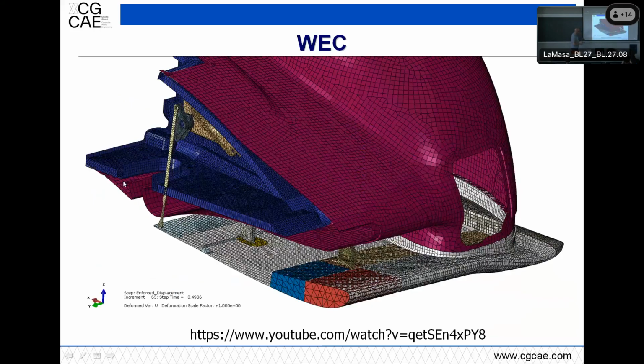And we did it virtually with some rubber layers in the middle of the laminate, and also some very thin ply laminate to allow for this. Clearly, you have the displacement, and you need to be stiff enough not to have a shear movement of the trailing edge, and the stresses have to be clearly below the level. In this case, the deformed shape was passed back to the CFD guys to check what would have been the drag reduction coming from this movement of the trailing edge.